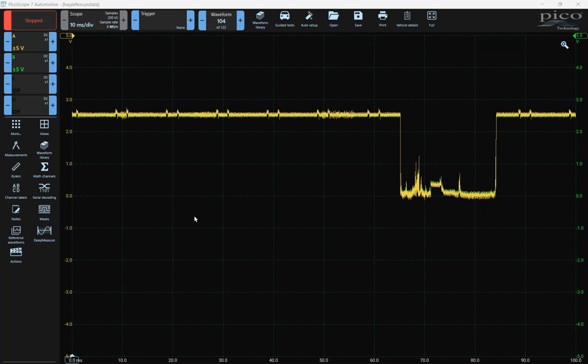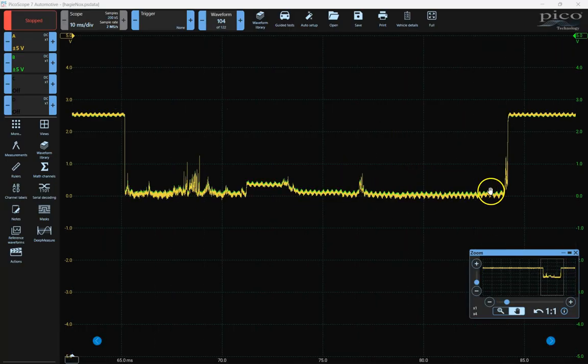In this fifth lesson, I'm going to take a closer look at the failure that I had in the last video, where we had an intermittent short to ground of CAN high on this passively terminated CAN network for the aftertreatment bus. We can see here that when the failure occurs, when we are shorted to ground, or the wire-to-wire short to the NOx sensor ground actually of CAN high, we can see that CAN high and CAN low both basically went to nearly 0 volts.